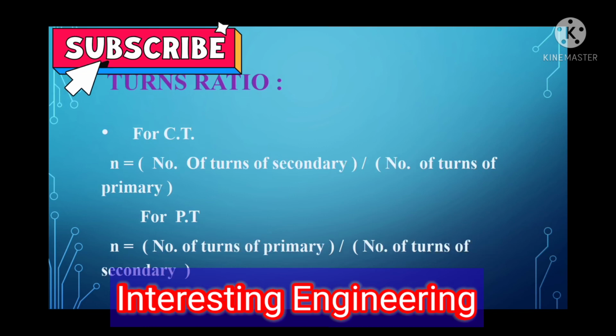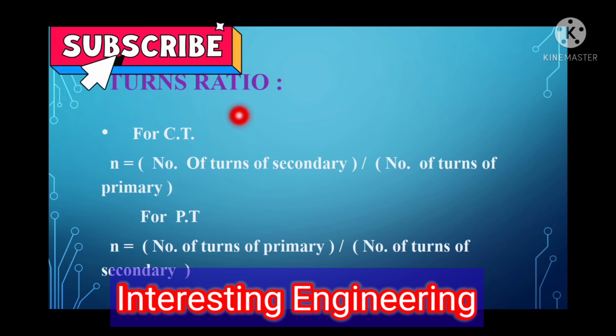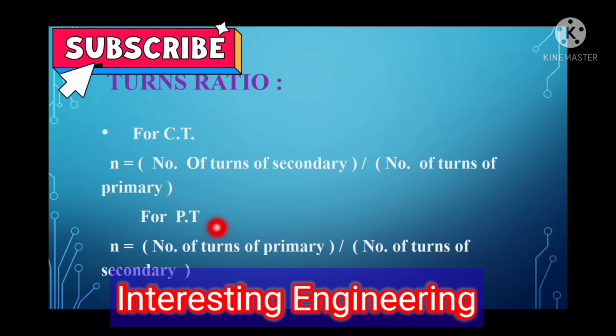The next ratio is the turns ratio, and for current transformer it is denoted by small n. n is equal to number of turns of secondary by number of turns of primary, and for potential transformer it is number of turns of primary by number of turns of secondary.